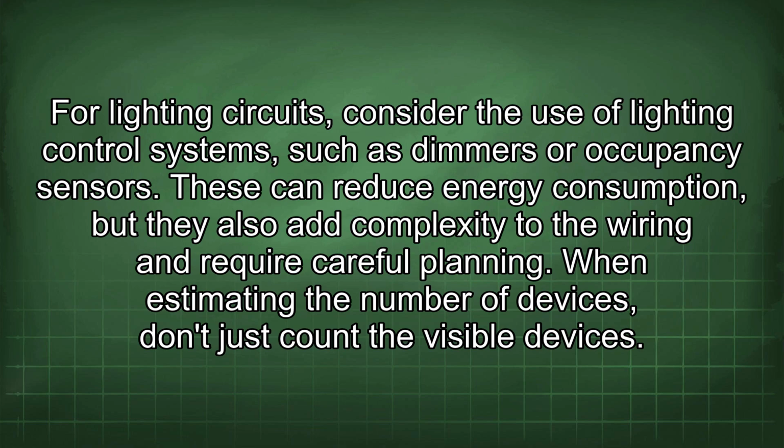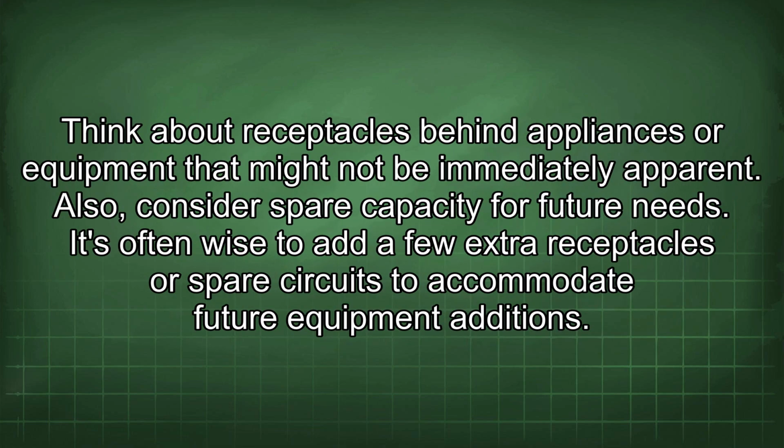When estimating the number of devices, don't just count the visible devices. Think about receptacles behind appliances or equipment that might not be immediately apparent. Also, consider spare capacity for future needs. It's often wise to add a few extra receptacles or spare circuits to accommodate future equipment additions.